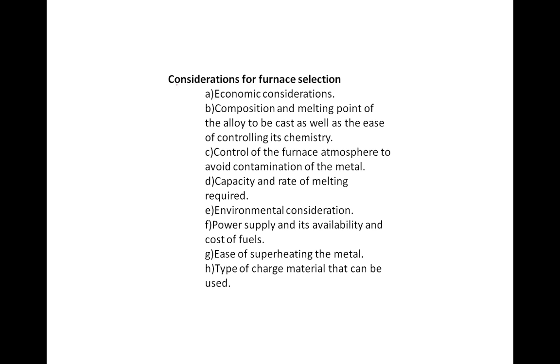Now, how are you going to select the furnaces? To make the furnace selection, these are the various points to be considered. Number one is economical consideration, which means cost. Then the composition and melting point of the alloy to be cast. Then control of the furnace atmosphere to avoid contamination of the metal, so that no reaction will take place with the molten metal.